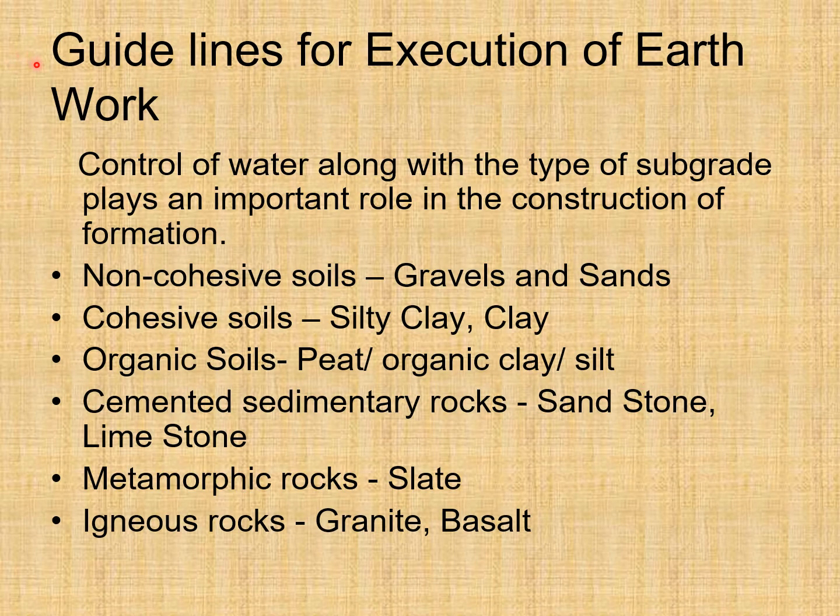Guidelines for execution of earthwork. Control of water along with the type of subgrade plays an important role in the construction of formation. So in this regard, a number of things are to be considered. Non-cohesive soils like gravels and sands must be preferred, and in the case of cohesive soils, silty clay or clay soils may be there.